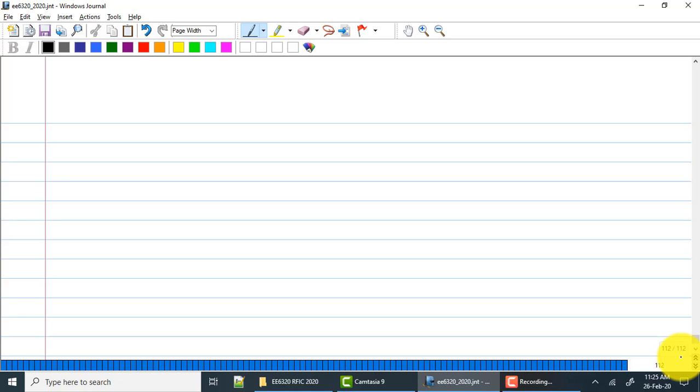But in general, you can already tell that the common source LNA will have an input passive gain, right? Which this one does not. So as long as the input Q is large enough, you could make a statement that the narrowband common source LNA will in general be better than this one because of that.